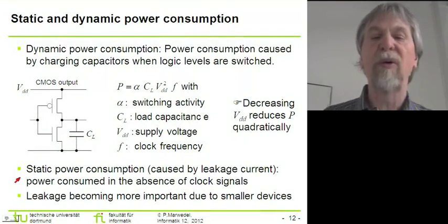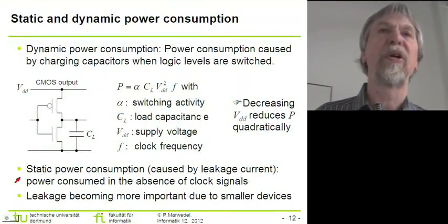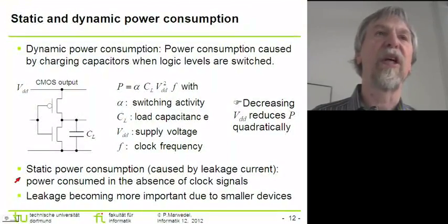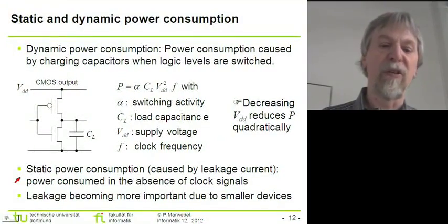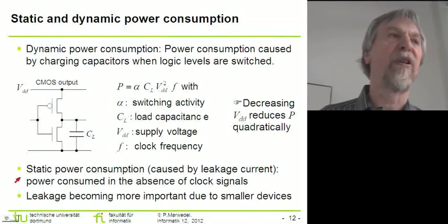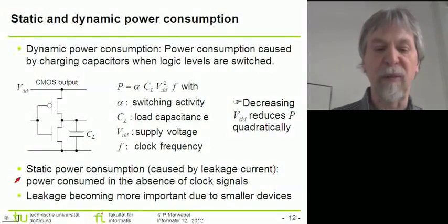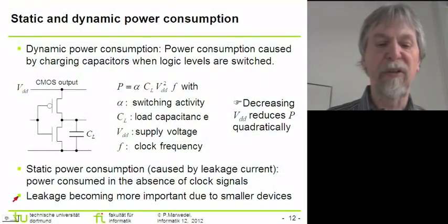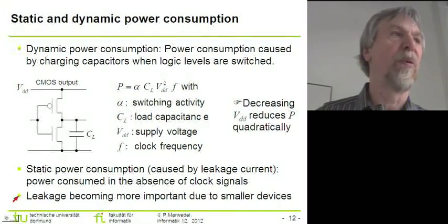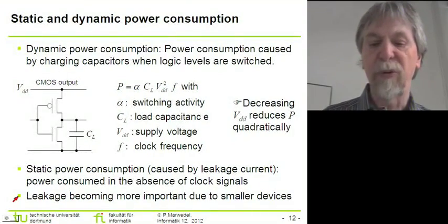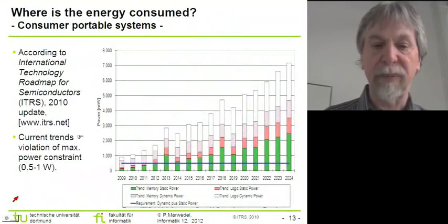And we know from the people who are working on the semiconductor technology that the contribution of the static power consumption is increasing when we work with smaller and smaller device dimensions. So therefore we know that this leakage is becoming more and more important as we move towards smaller devices.